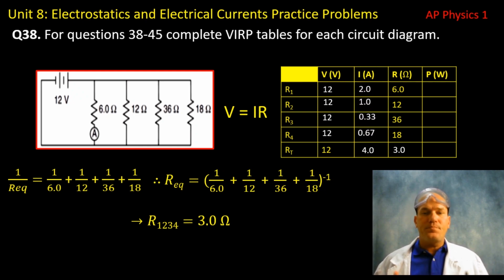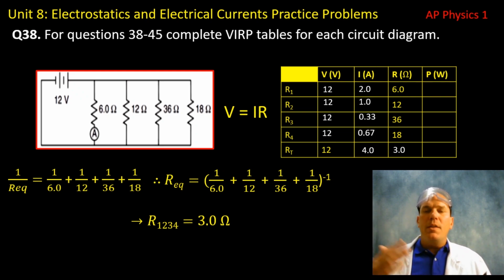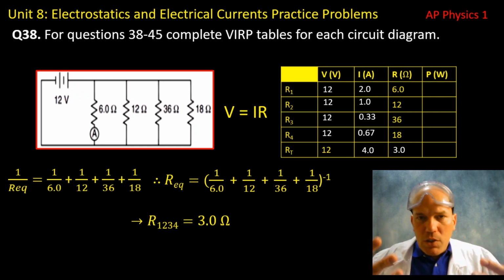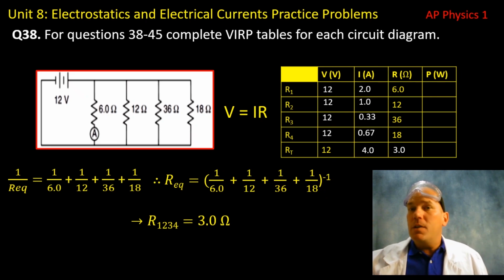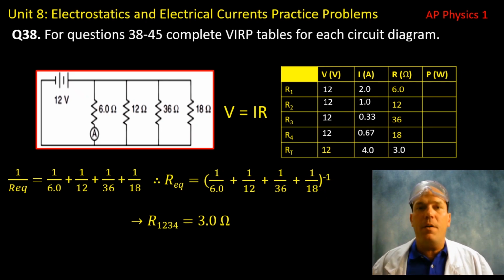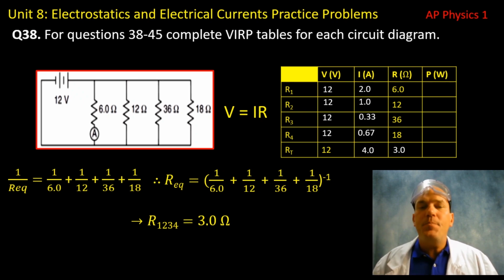Now that we know that, we can apply that information to the remainder of the circuit. If we know the total amps or total current through here to be 4, then you can start calculating all the other currents because you have 2 out of the 3 values for Ohm's law. You have total voltage. You got that because you understood, hopefully, that it's all parallel. So it's 12, 12, 12, 12. And we know the resistors. So we could have just right off the bat calculated the individual currents and then added them all together. And they should all equal up to 4.